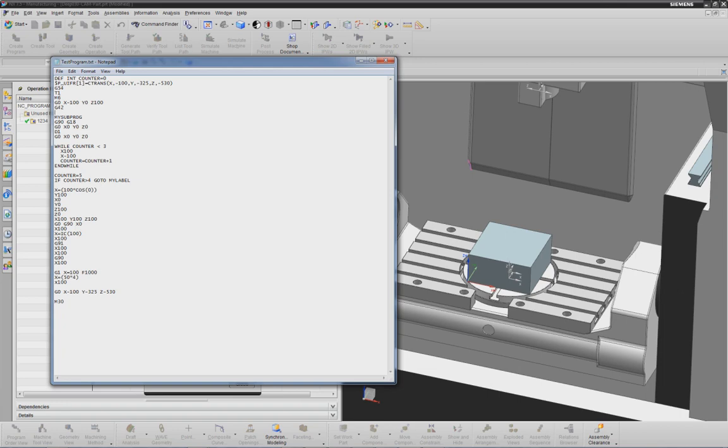So we activate radius compensation to actually compensate for the first time. We should move to G0, X0, Y0. I don't need Z again, Z is already 100. So then we are in this coordinate, but already with active radius compensation.